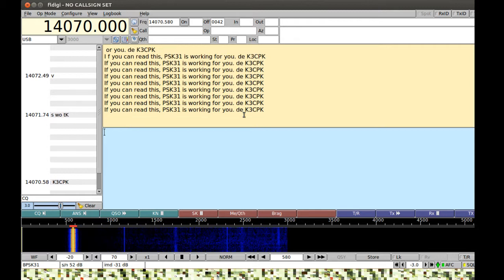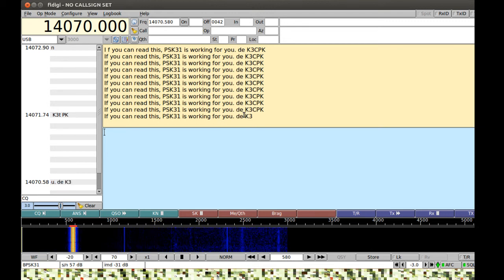What I'm seeing here is, as I change my FFT settings over here, it's changing the way this looks. Ooh, see that rate, 60 FPS? Yep. Drop that down to 25. And it still didn't. I'm just trying to think of everything that would reduce your CPU load right now, because that's usually the problem that people have. And also, if all else fails, try a loopback cable and see if that has a better result. I only have a single jack on this thing. It's combined, mic. I'd just swap to the RTL.